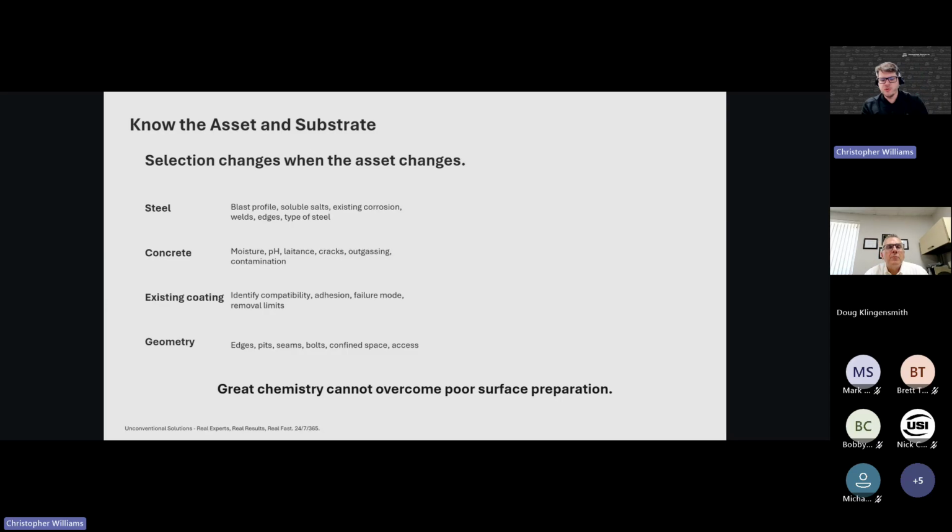But the reason we do it that way is you can peek into that container when you're doing your inspection and very easily see, hey, is there damage in here? Am I seeing that other color peek through? Is it time to start recoating? And these systems are built in a way that it's easy to recoat, right? We know the product that's in there. We know that we can go in there and rough up some of those surfaces and apply another coat. If the coating's been in there for a really long time, a lot of times you'll see that it's damaged beyond that. And you're going to have to blast the whole coating off.